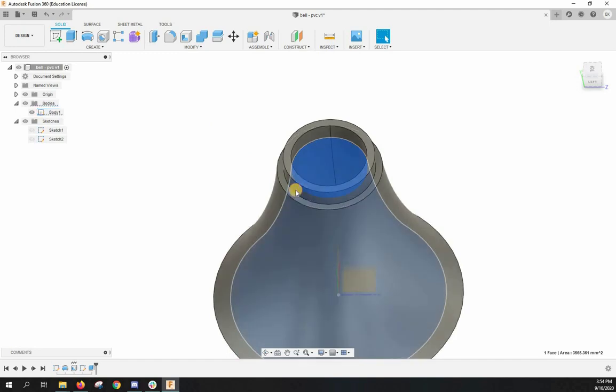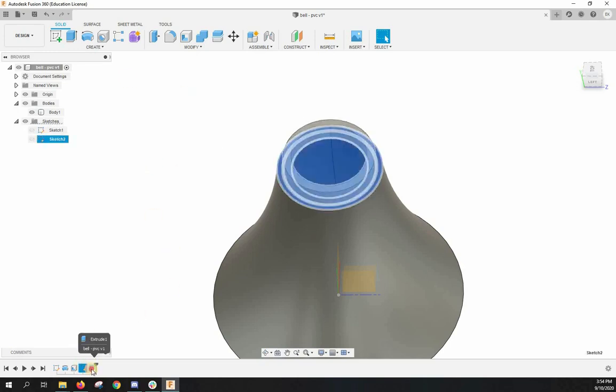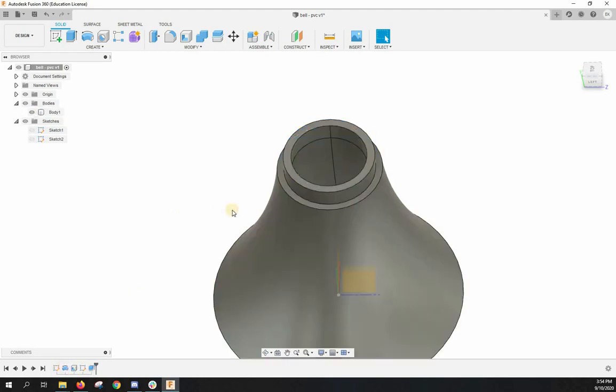And usually for things that require a sketch, the sketch is right before. It isn't always. It depends on whether you did all your sketches beforehand, but if you do sketch and a feature and a sketch and a feature and a sketch and a feature, the sketch before is probably going to be the one that defines your extrude, your revolve.